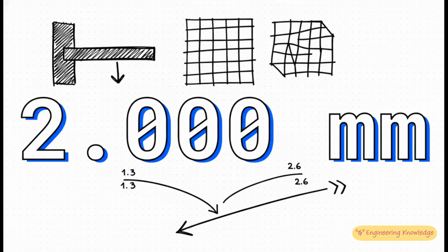So why does all this matter so much for your actual projects? Well, consider a really simple cantilever beam test from our sources. Traditional hand calculations tell us the true deflection is exactly 2.000 millimeters. But just by choosing the wrong element formulations, falling into those traps of hourglassing or shear locking we just talked about, analysts got predictions ranging from roughly 1.3 all the way to 2.6 millimeters. That is literally double the deflection. Just imagine 2 analysts working on your project, making critical, expensive design decisions, and getting wildly different results just because of the element they chose.